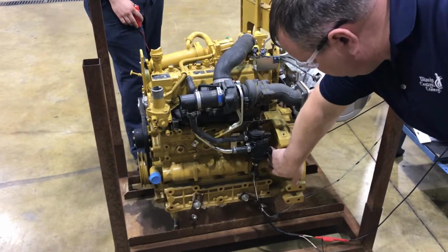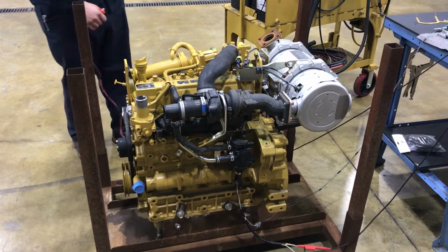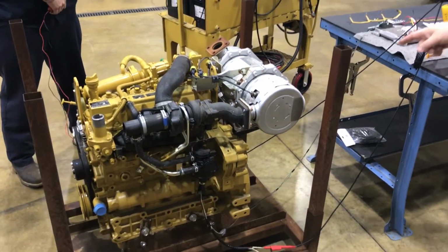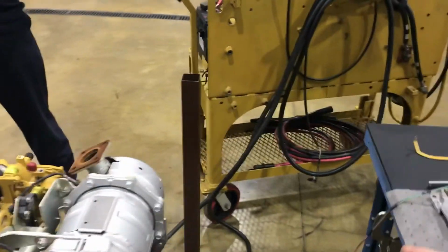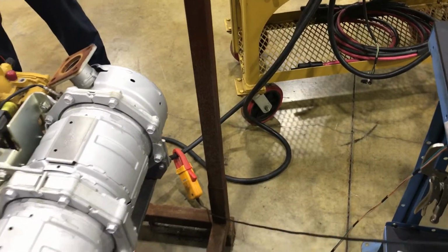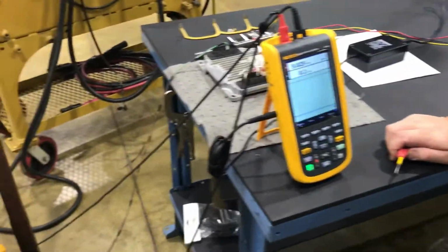The setup on this, if you look over here on the 3.3, is that we're actually going to the cam sensor. So we're teed into the cam sensor and going to look at the signal off of that, signal and ground. You can look right over in here, you can see we've got a current probe on the positive battery cable. So if I bring that over and look at it on the scope, it's going to look like this.